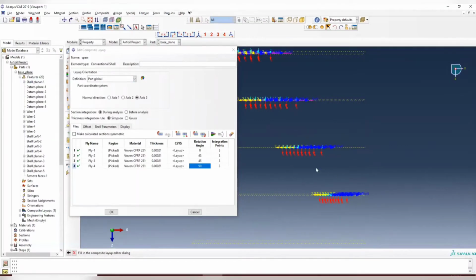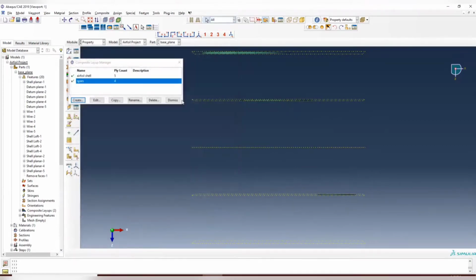The reason we need to split the ribs and the surface, the face sheet, is if you select the face sheet, the normal will be pointing to the Z direction, sorry, to the Y direction. But Y direction is in plane, so it doesn't apply to the ribs. That's why we need this one. So click OK for that.